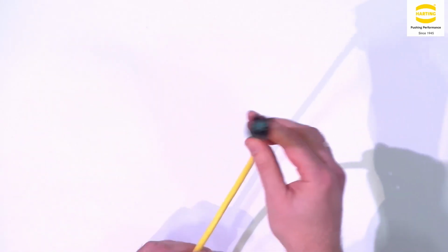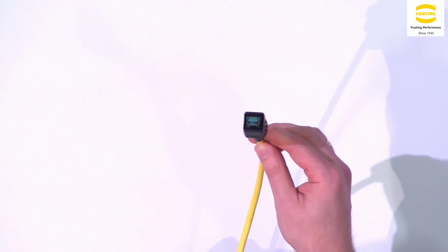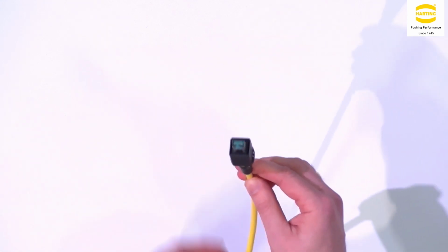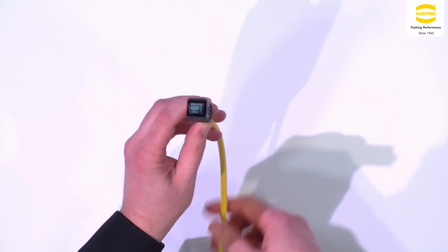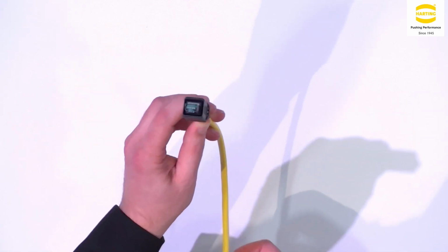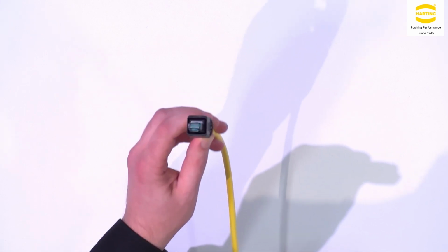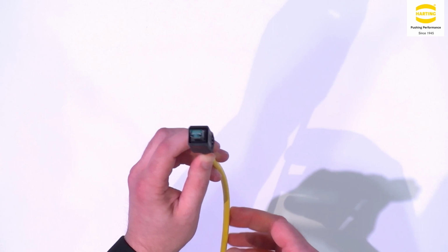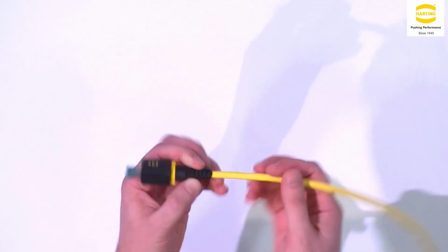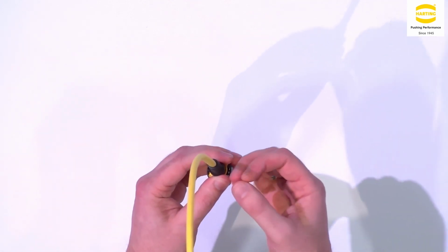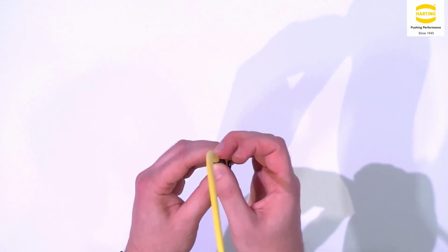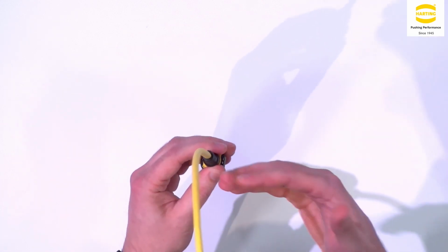So here, for example, we have an RJ45, a well-known RJ45 interface, but with a special housing. This special housing offers a quick mating and quick locking system where we can easily mate and unmate it. We have an O-ring inside, and on the top side we have a cable jacket which really fits to the overmolding material. So this gives the connector the whole protection of IP65 and 67.